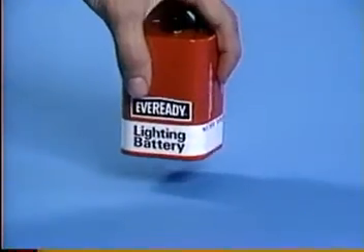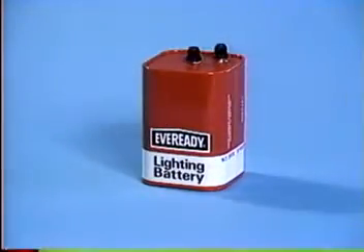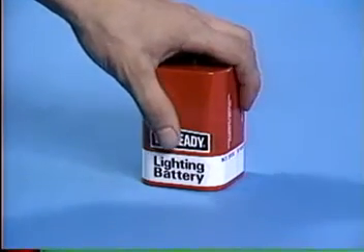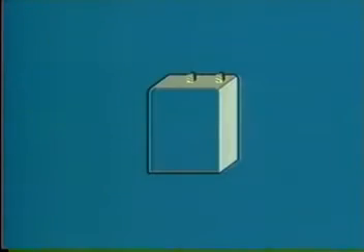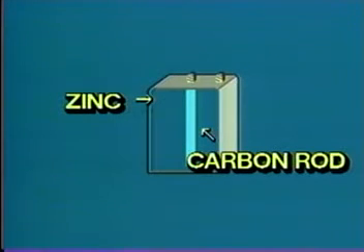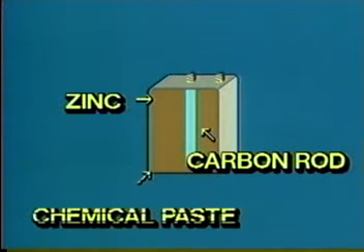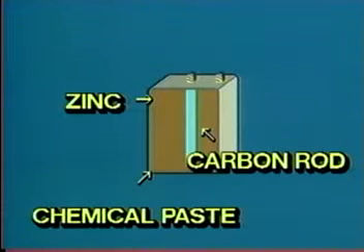For the power source, you will use a 6-volt dry cell battery. So let's first find out just how your power source produces its voltage. The battery develops its voltage by converting chemical energy to electrical energy. The shell of the battery is a metal can made of zinc with a carbon rod suspended in the center of the zinc can. The rest of the can is filled with a chemical paste, composed primarily of zinc chloride.